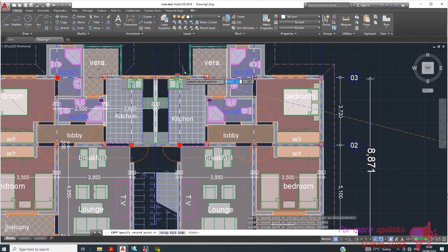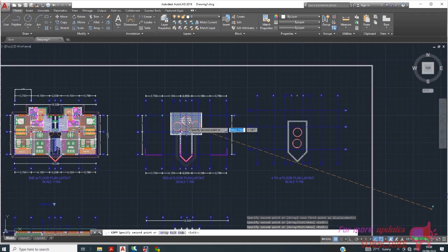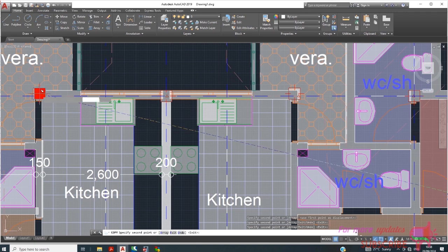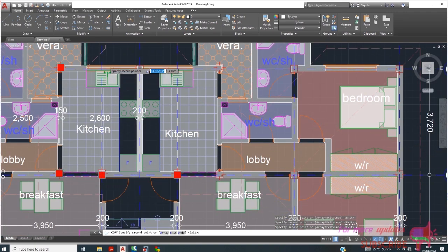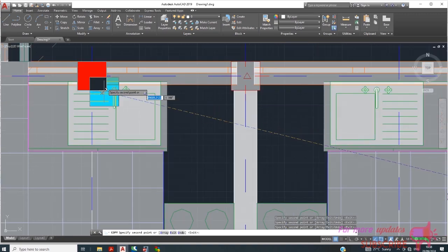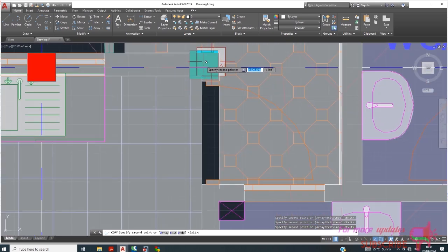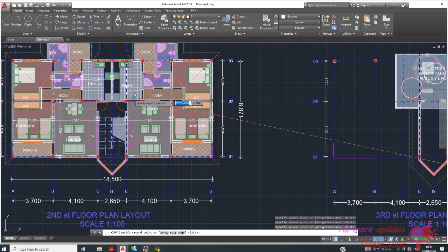So I will also do this. This is basically water tank, and there's also water tank around. There's water tank at that floor, if you can see here. So I must have 4 columns at this point to support that water tank. So I will have a column there and there, all the 4 corners. I also need another column here, another column there. Finally, another column at this point, and at that point.